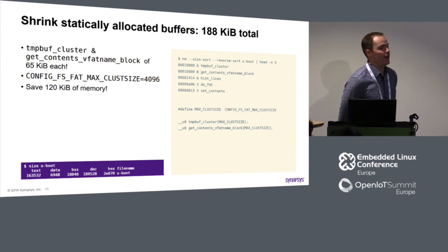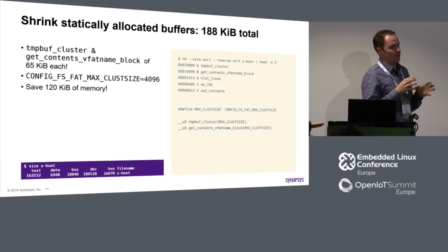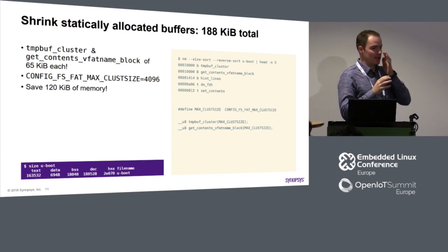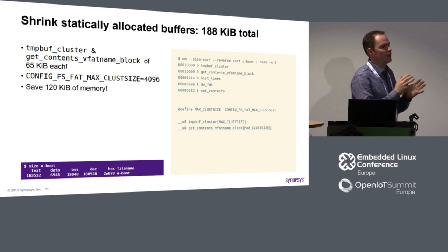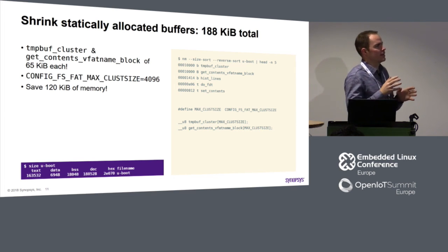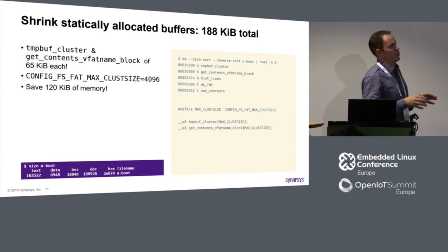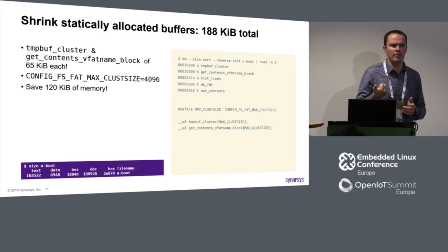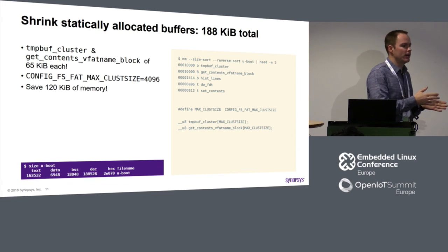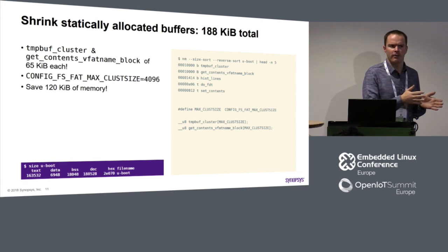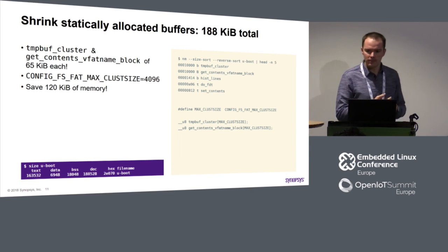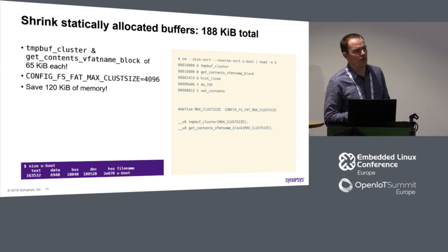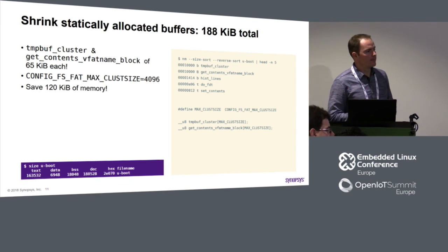The spoiler is we may have an even more stripped down U-boot, which does only one thing that we want it to do. It loads from only one media typically, and doesn't throw debug messages. But it is very tiny, so it could fit in like one page of memory. For example, I think on the IMX platform they have SPL which fits into one page, like 4K or something. No, it's 32 or so. Oh, 32. Well, anyways, it is quite small. I do believe you can make a bootloader as small as one jump instruction.